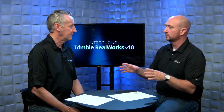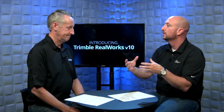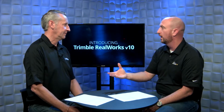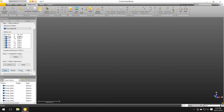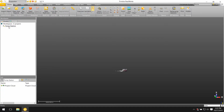workflow. The other thing you've also done is Trimble Realworks used to have effectively 3 modules, and you've now condensed that to 2. Can you talk a little bit about what that is and why that helps? Yeah, I think that's a pretty important part of this consolidation part of the workflow. We've broken it down into one, which is registration, which is the important first step of a point cloud, bringing those different scans together, consolidating it into a solid point cloud that you can start extracting information from. Then we just have another mode, which is just production. So what am I looking to extract out of the point cloud, and how can I get it out fast?